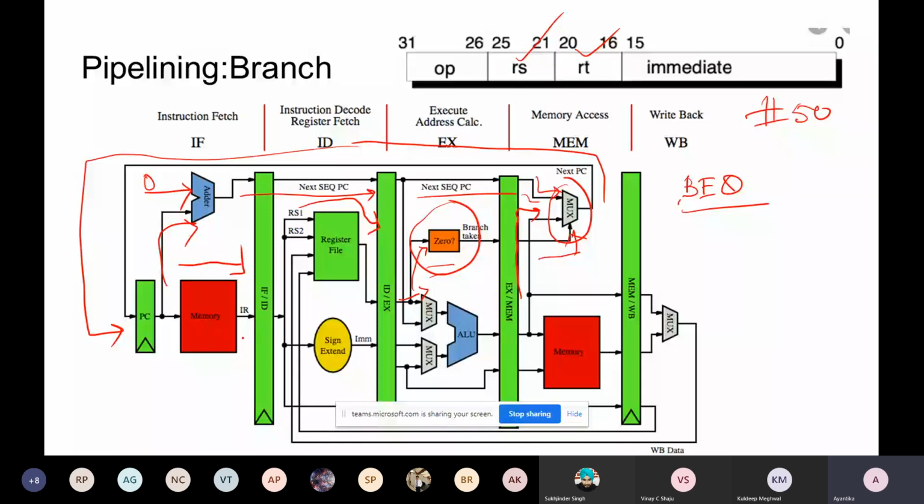Now you see, when your instruction register is fetching that type of instruction, one input is coming from this register file, and the other input is coming from this immediate part, that is whatever you are getting in this instruction register. That immediate from the instruction register, you cannot take directly. There is a concept of sign extension, and after that you are taking these two values as inputs to this ALU. So that's why you have two mux here, mux 1 and mux 2.